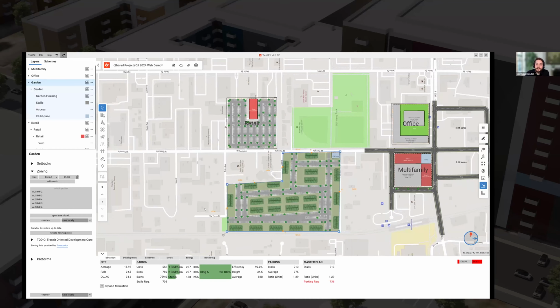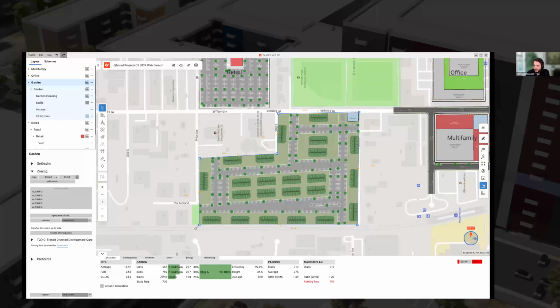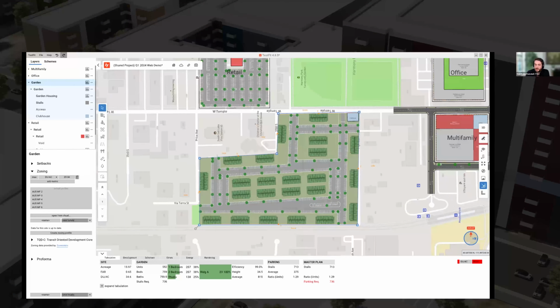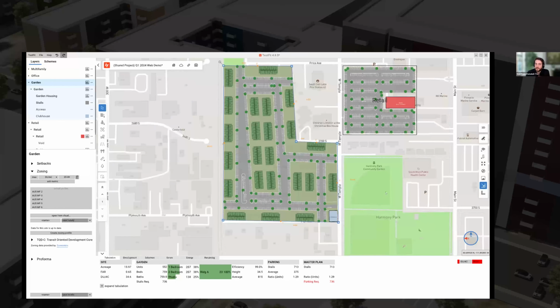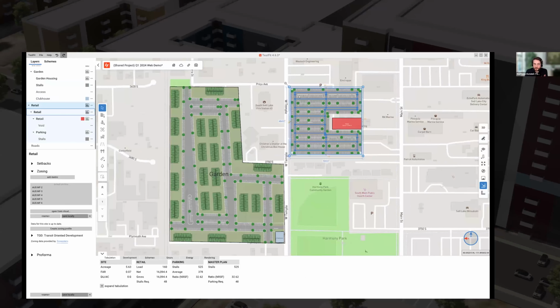I'm going to click and define that. Now it's rotated my whole screen, and this is my new project north. We still retain the information for true north versus project north, and I can simply click on each of those icons and swap between the different ones. So that lets you get more accustomed to the way you're used to viewing it.